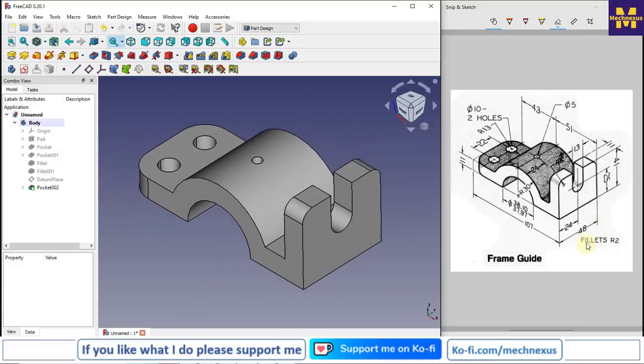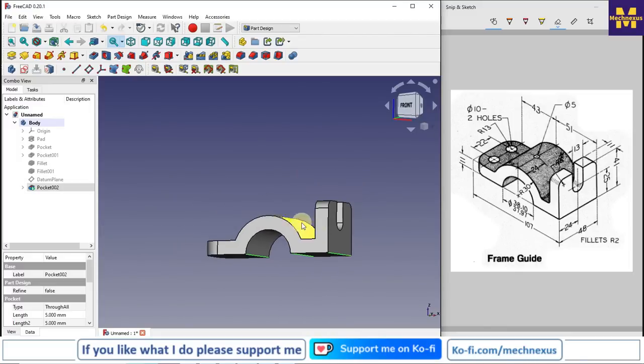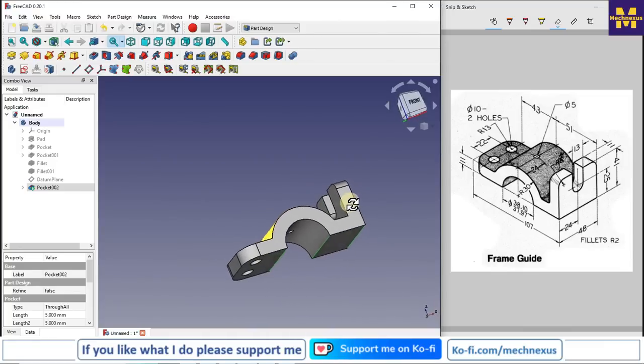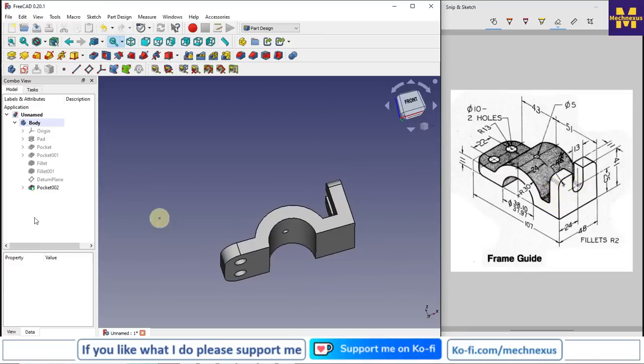And now here a common radius R2 is given, so I will give the common radius. So I will select this edge, this edge, this edge, not the bottom, I think so where it's showing I will give on that portion, I mean at this edge and this edge and inside one, because here I see a very sharp corner.